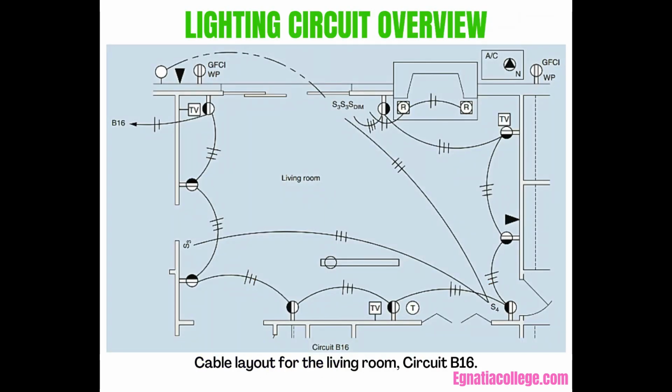Lighting circuit overview. This figure shows a sample device and wiring layout for the living room area that is connected to circuit B16, a 15 ampere circuit. The home run is brought from panel B to the split-switched receptacle to the left of the sliding door. Split-switched receptacles are discussed in Unit 14. A 3-wire cable is then carried around the living room, feeding in and out of the other split-switched receptacles. This 3-wire cable carries the black and white circuit conductors plus the red wire, which is the switched conductor.